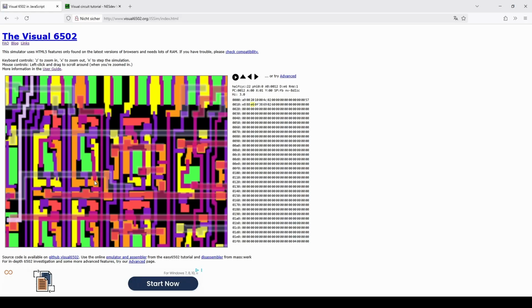and that then powers this gate now, right? Which lets the source here, this yellow area, drain to ground. That then causes this to be pulled low, and that doesn't really have an effect on the 5 volts getting through, because again, diode connected.